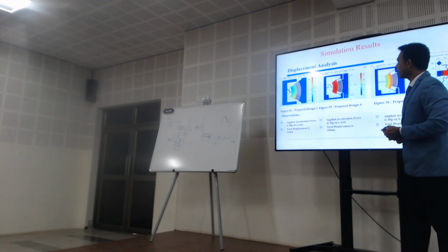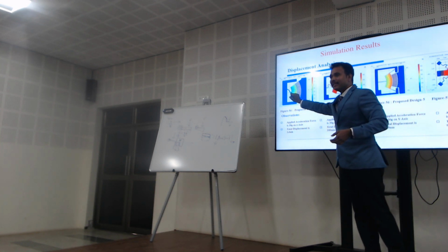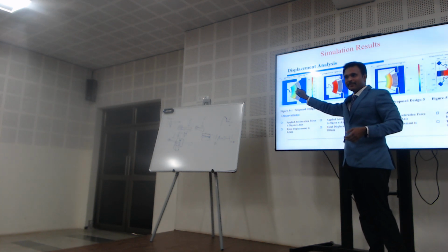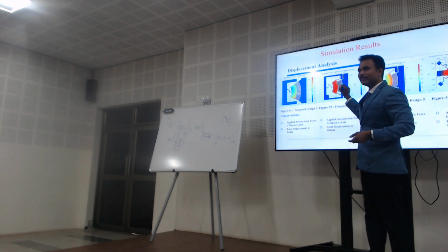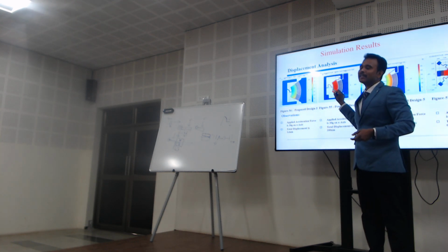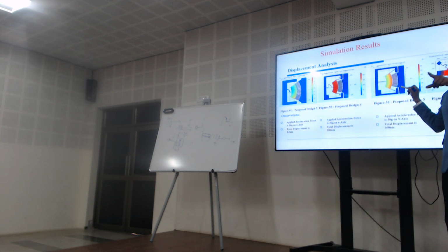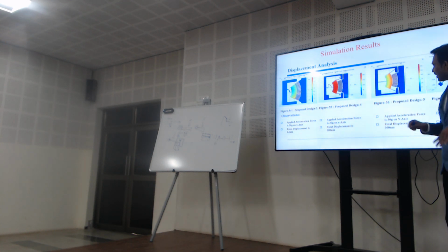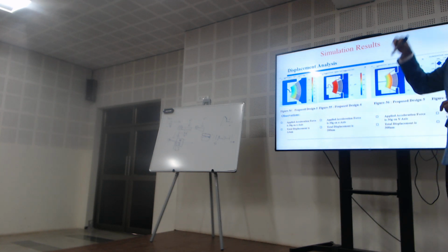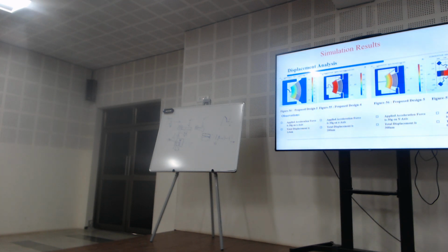Here I said this is also a good design, because here we don't have any other support, only this support. Due to that we are not getting good stress analysis here. So here equally we can see, again we are getting very good stress analysis, but here we are not getting differential capacitance. This is only for one direction. We are saying that more stiffness is there. Due to that stiffness, if I apply 30G, it can't move. Maybe here I can apply 150G, and then only it can move. So this is my final design.